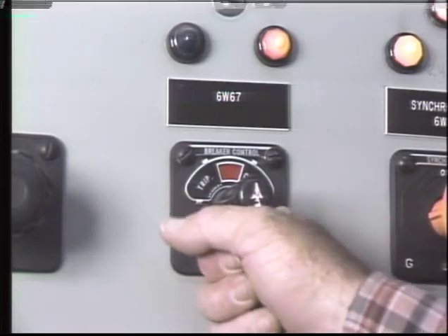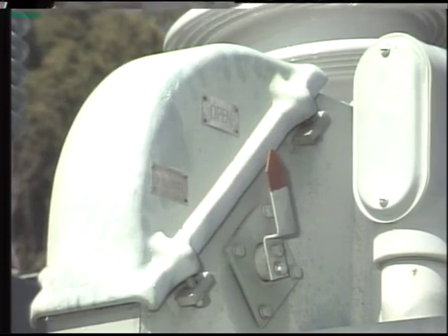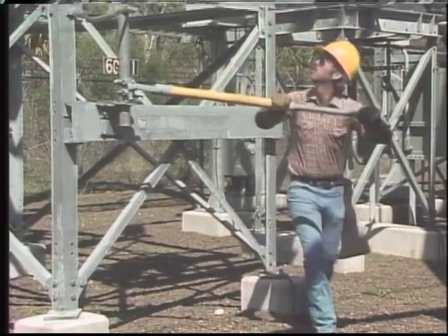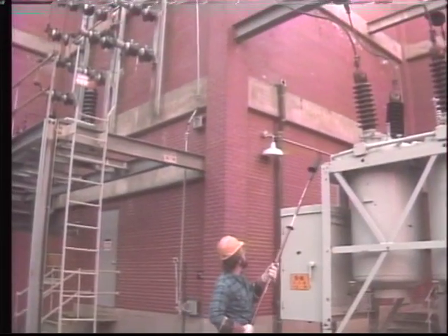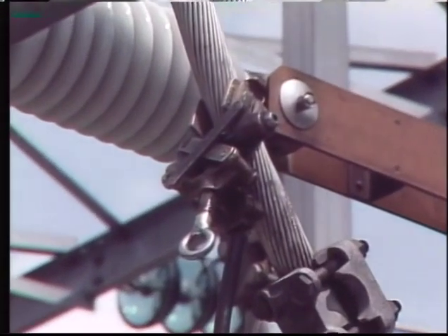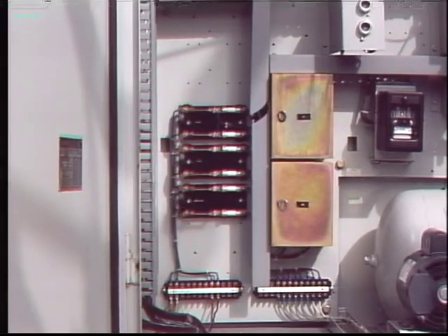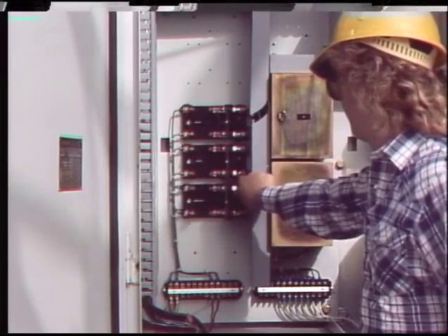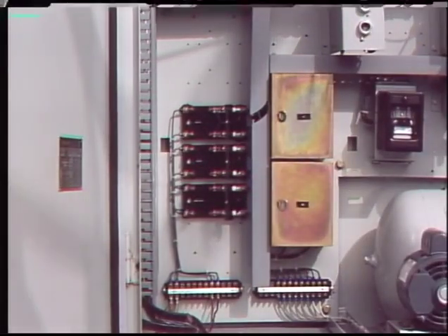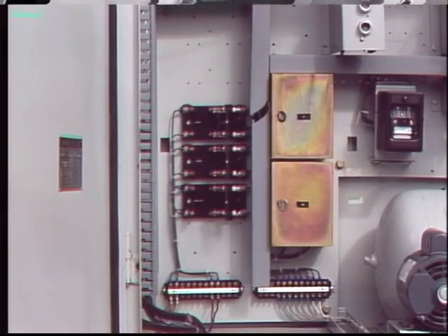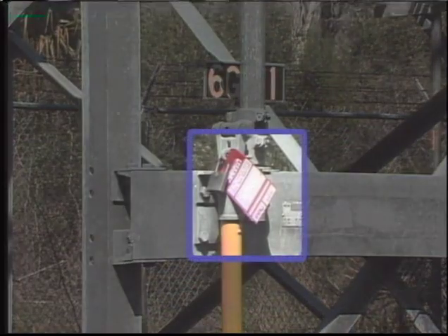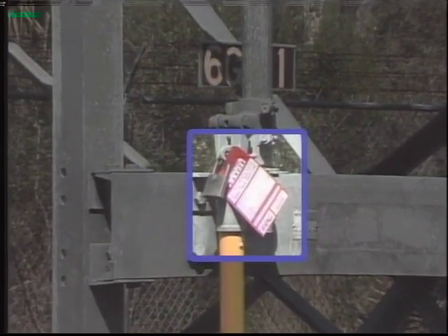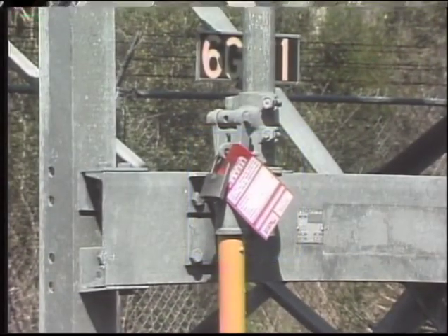In general, a breaker is taken out of service only after the proper clearances have been received. When a breaker is taken out of service, it's first de-energized by opening the breaker. Then it's physically isolated from the system. The breaker is tested for dead and properly grounded. Control circuits at the breaker are also de-energized. Control circuits provide power for trip coils, closing coils, heaters, and other electrical devices in the breaker control cabinet. All appropriate switches and circuits are tagged according to company policies to warn others not to operate the equipment.